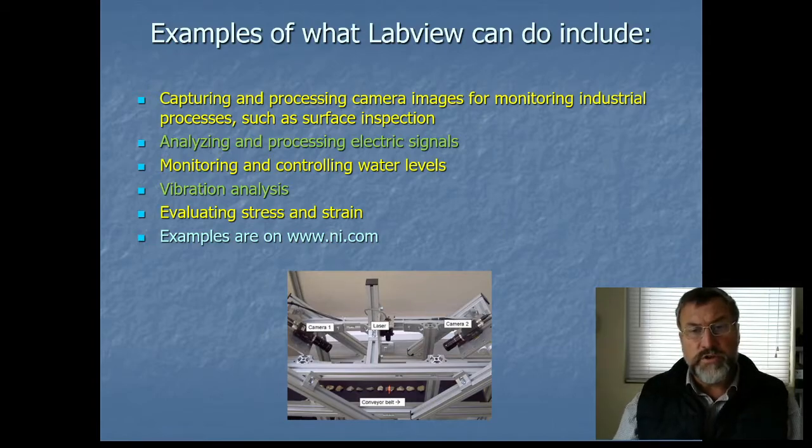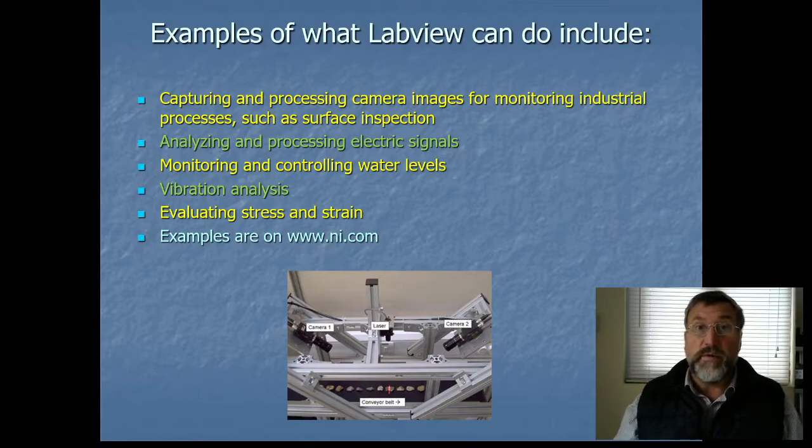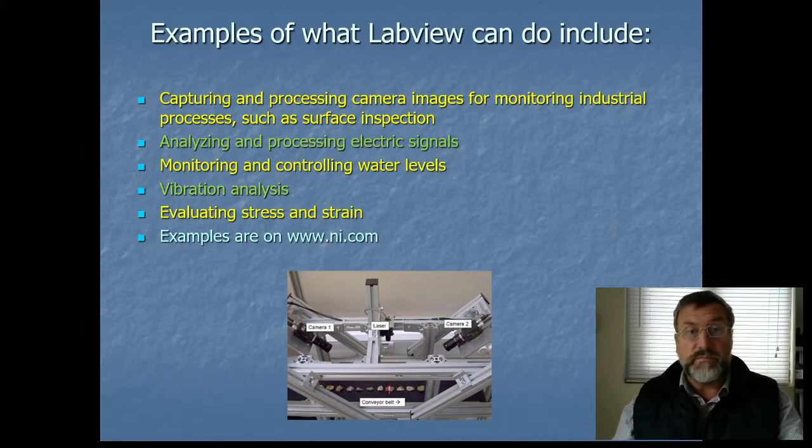So what engineers tend to do is build a model, mount lots of strain gauges on it, apply certain forces, and see whether the strains they're getting are in line with what the finite element analysis they're running is telling them. And if it is, then that's validated their models. Otherwise, there's a danger of producing phony data, which you have a lot of faith in, but there's not really any validity to.